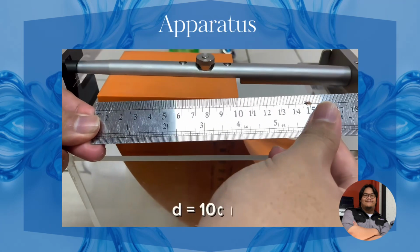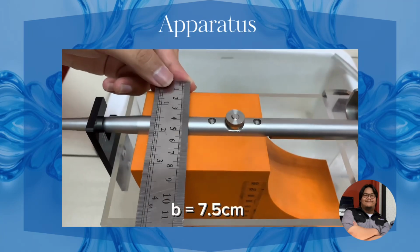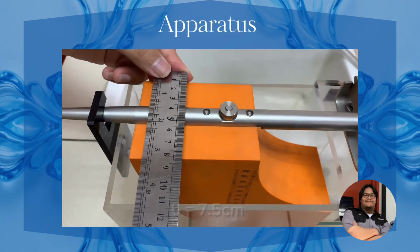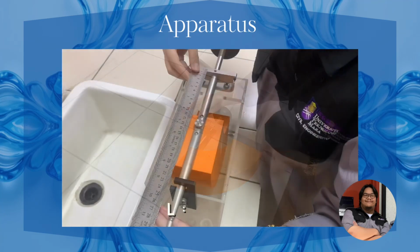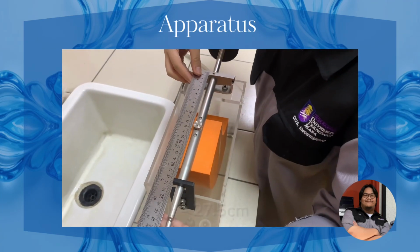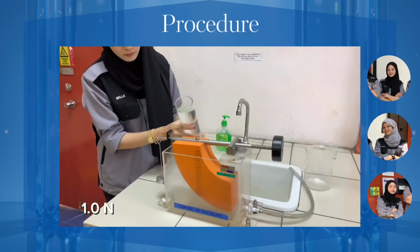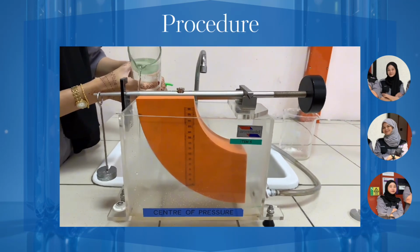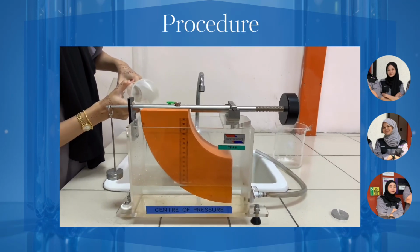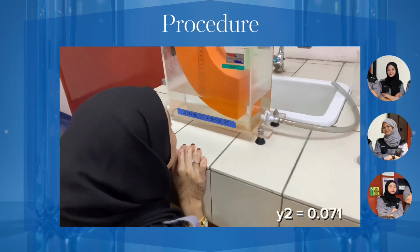First, we start by measuring the length of the quadrant using a ruler. Then, we proceed to measure the width of the quadrant carefully. Finally, we measure the height of the quadrant from its base to the top edge. For this experiment, we used a load of 1.0 Newton, then water was gradually added to the tank until the balance rod reached equilibrium. The recorded values for Y1 is 0.129 and for Y2 is 0.071.